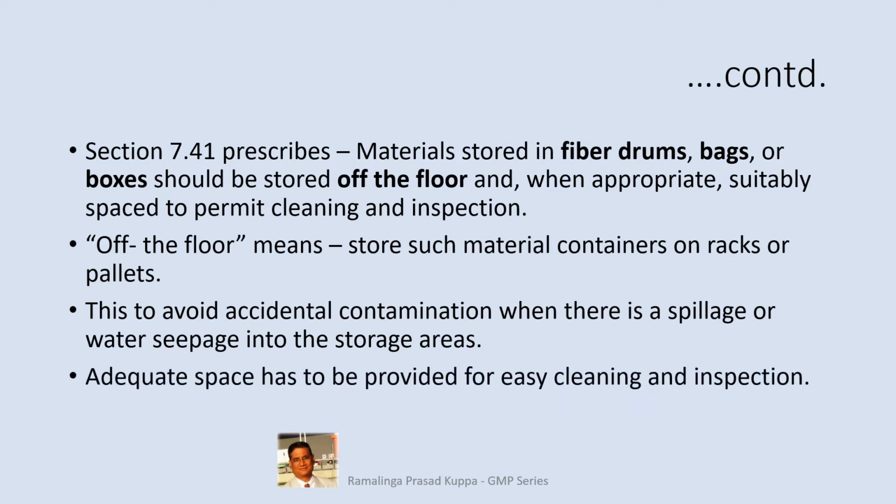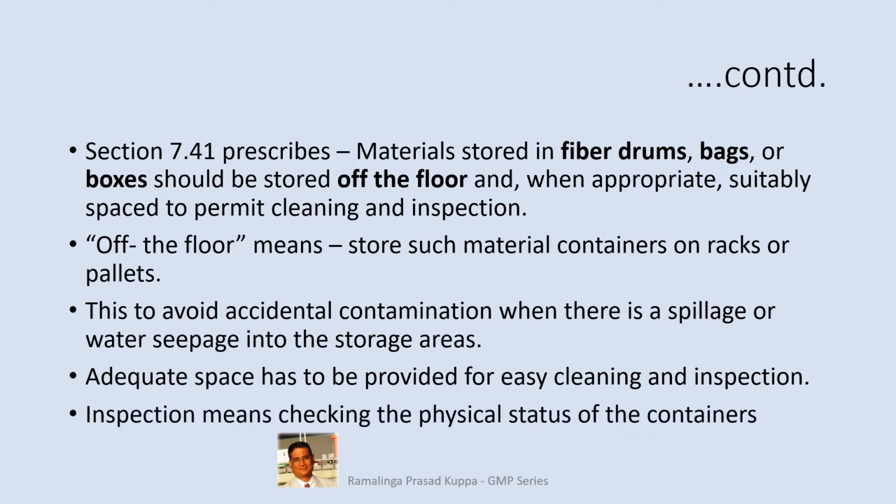Adequate space has to be provided for easy cleaning and inspection. There should be adequate space around the pallet on which the materials are stored. This is for easy routine cleaning for good housekeeping. Inspection means checking the physical status of the containers. You have to check for any physical damage as a part of inspection.